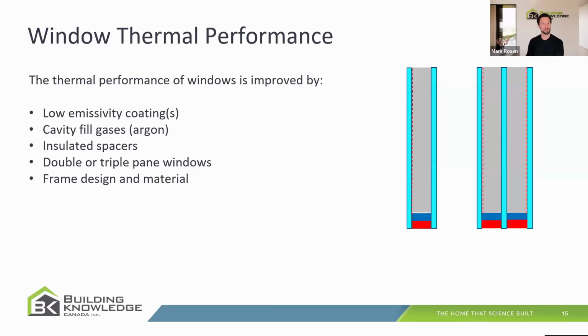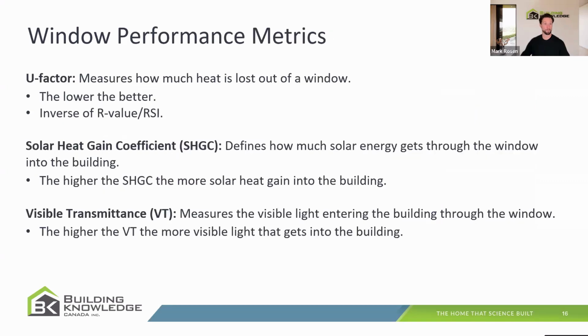And not to be forgotten, the frame design and material, which is not even pictured in our little diagram on this first slide, but the frame that holds your glass unit in place and connects it to the wall and the detail around that connection is critical for thermal performance as well as airtightness and water management in a big way.